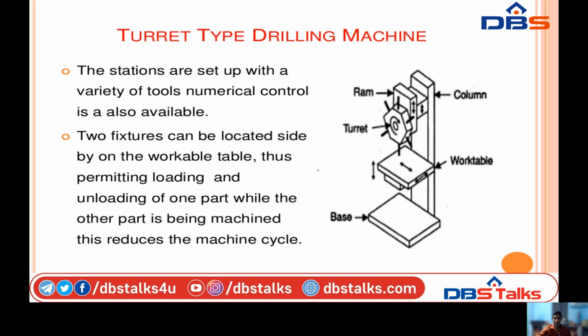Turret type drilling machine. Coming to the turret type drilling machine, the stations are set up with a variety of tools. In these, we can use numerical control also. Two fixtures are located side by side on the work table, thus permitting loading and unloading of one part while the other part is being machined. This reduces the machine cycle.